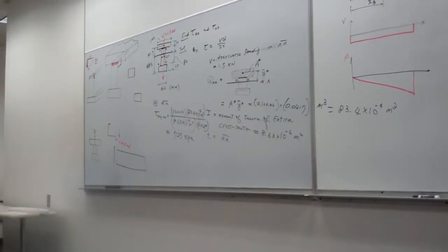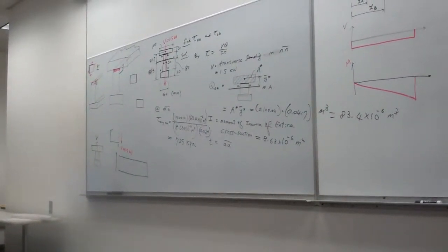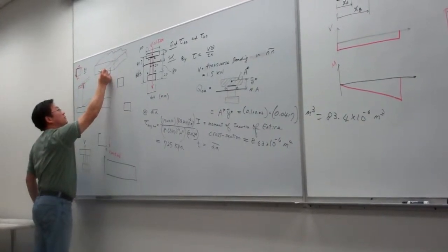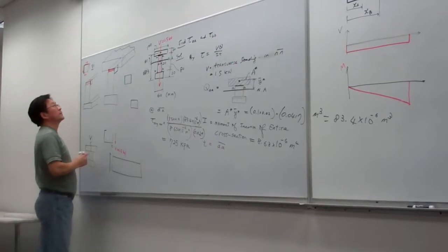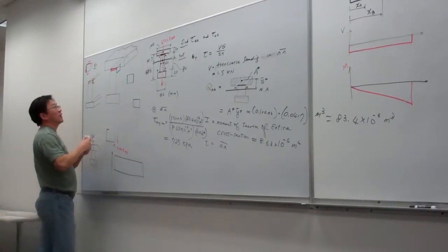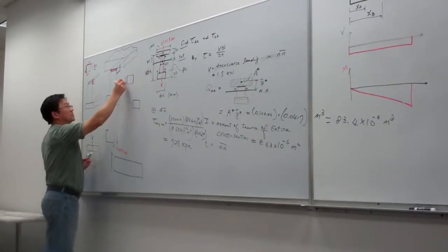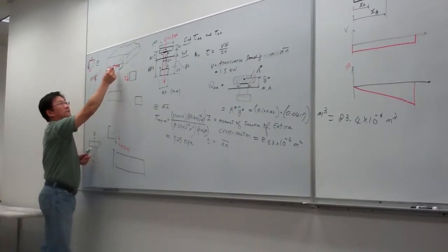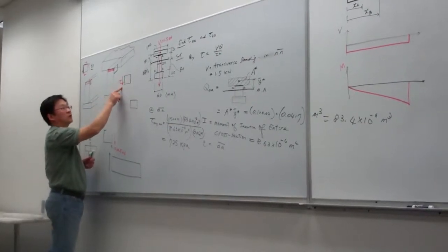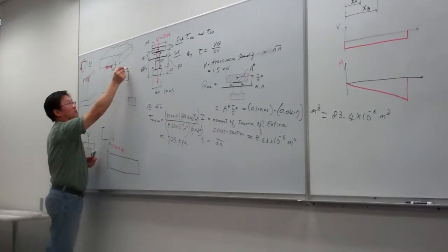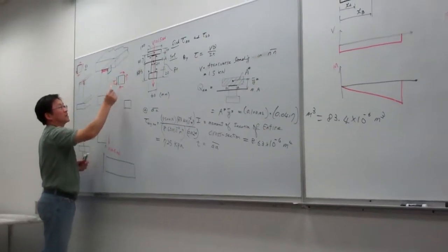Is that element the same one that you picked previously? Yes. Okay. So this edge is this edge. Okay. And then in this way, on this edge, that is the shear stress, right? On this side. So once again, once we know the shear stress on one side, we would know the shear stress on the other three sides like this.